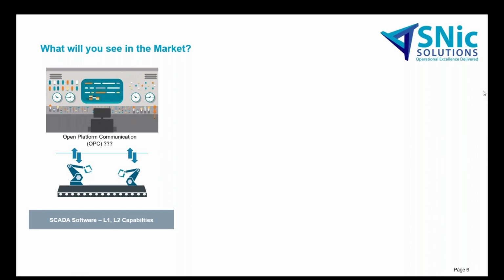So if the machine manufacturer had, let's say, pressure and temperature built in its machine or in its PLCs, you were okay to get pressure and temperature. But let us say a third parameter like a breakdown status, if that was not built in, then it would be very difficult to capture that data. But open platform communication and OPC servers make this easy to talk to modern day software interfaces.